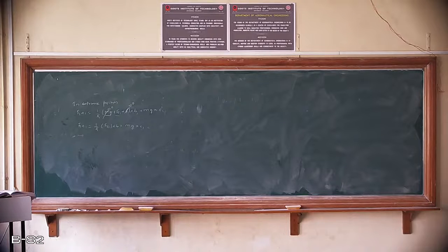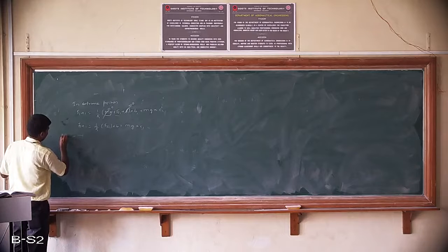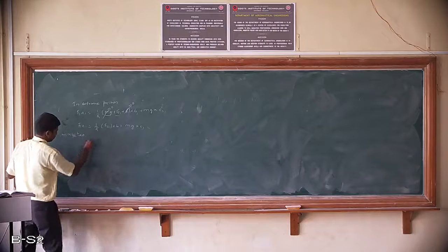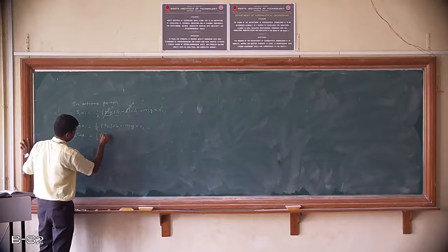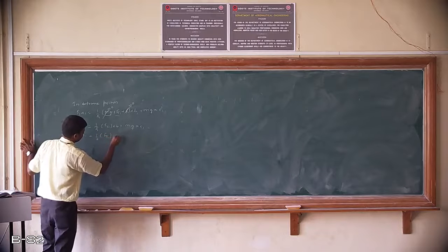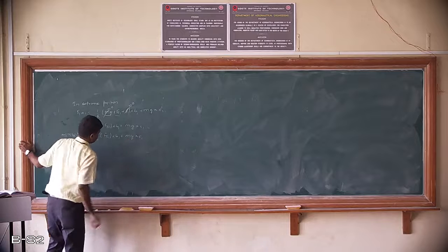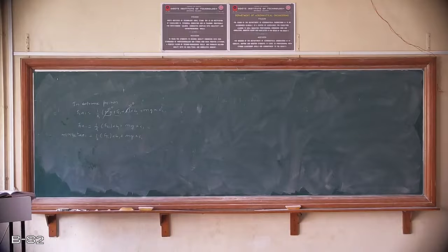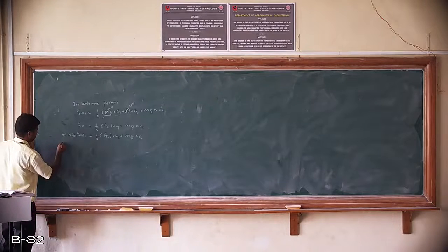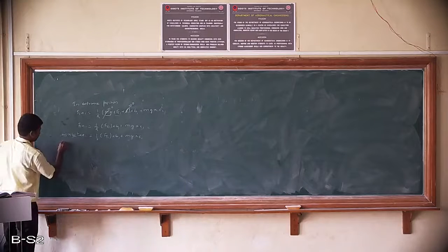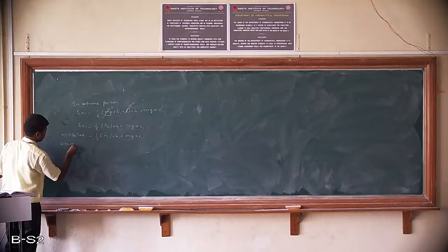F value we have not calculated, so we can calculate it by using the equation m1 r1 omega 1 square into A1 is equal to half into Fs1 into B1 plus mg into C1. So this is our equation. In this equation substitute all the values. The mass of the ball is given, that is 4 kg, into the radius r1, which is 90 mm, so it is 0.09 meters.